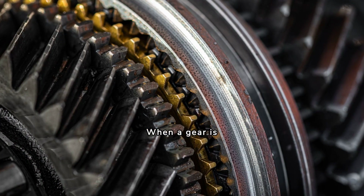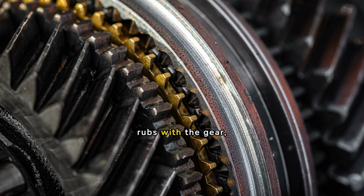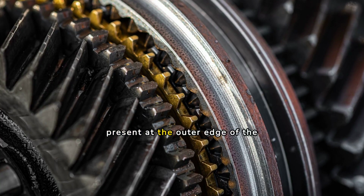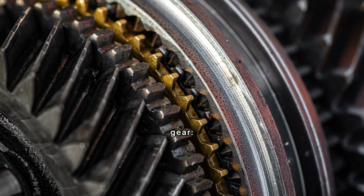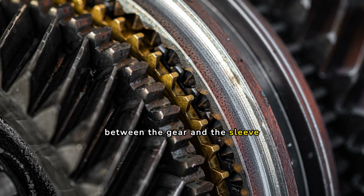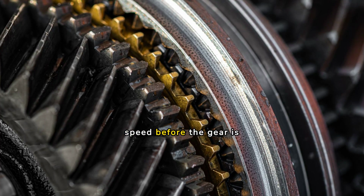When a gear is selected, the blocker ring rubs with the gear and locks with the straight teeth/spur gear present at the outer edge of the gear. The locking action increases the friction between the gear and the sleeve, hence matching their speed before the gear is engaged.